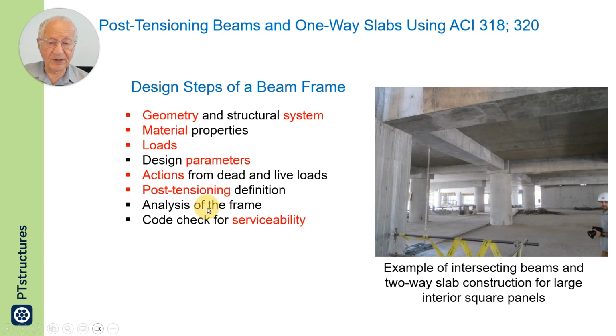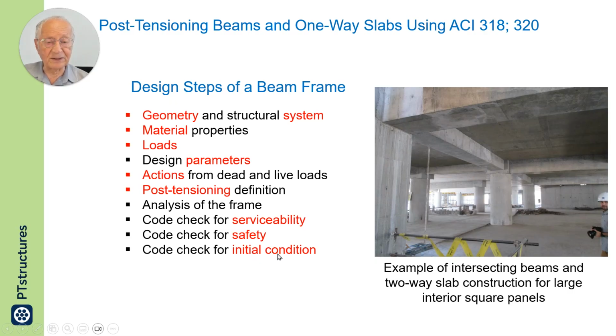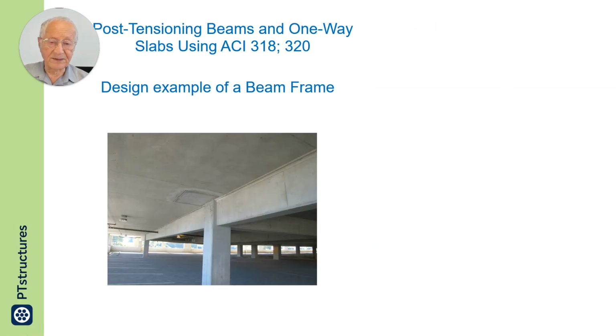We analyze the frame, check the frame for service condition from the analysis, and then check it for safety condition, and finally the initial condition, which is at application of jacking force. This will be the last of the three major checks, and we follow it by detailing of the design.